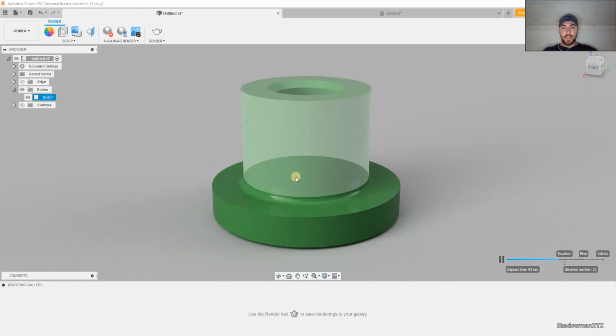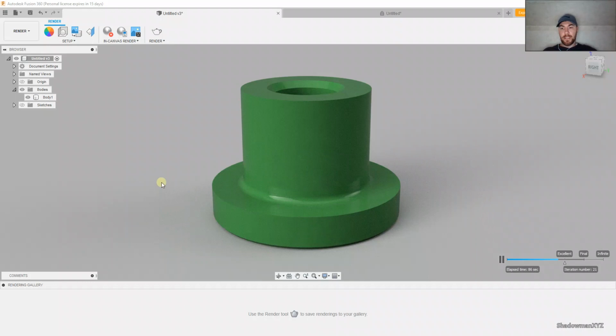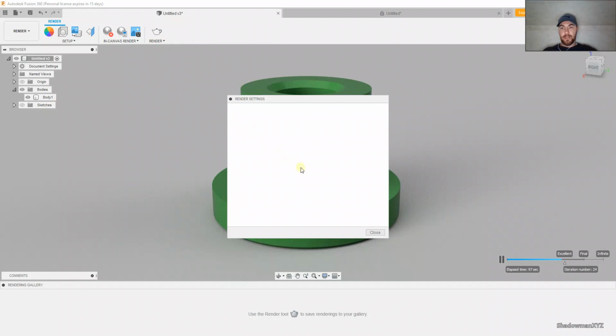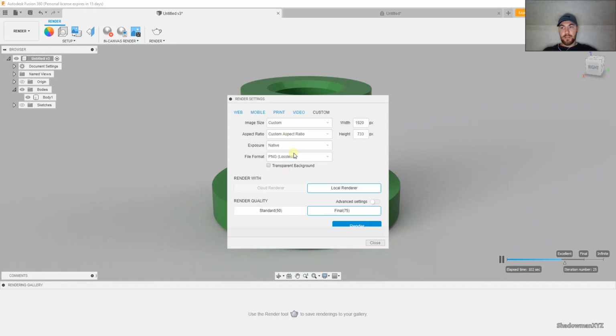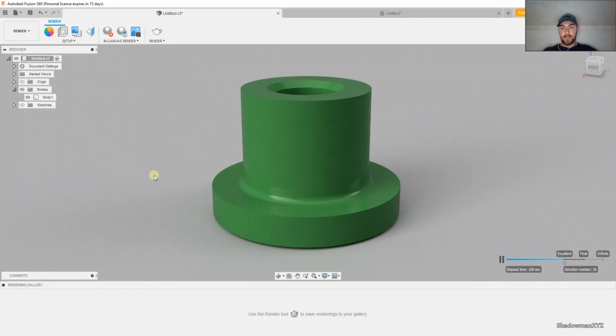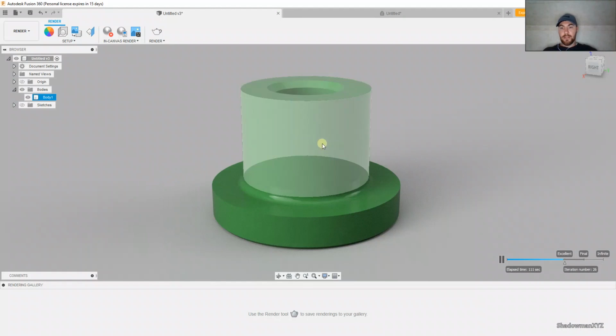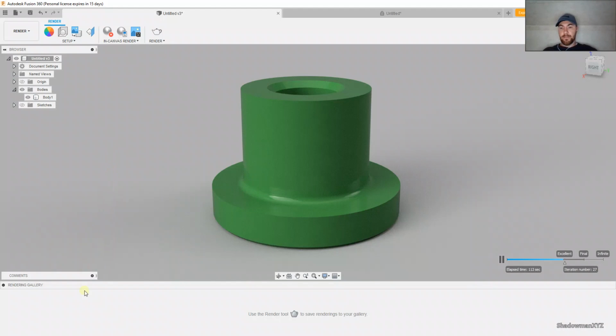It's looking really nice. If I roll my mouse wheel forward or back right now or move anything in this design, it will start over. So that's the only issue we have here. If you want to get around that, you can go right here to render, and render it in the background. In a little while, it'll be done. Just hit render. It's gonna render it as a PNG. It's gonna come out looking just like this is right now. It'll pop up down here in a little while.